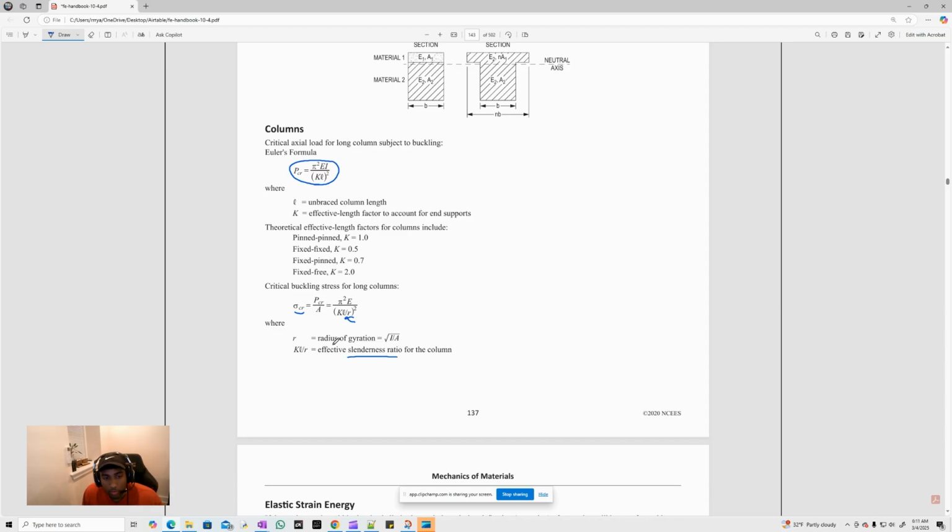You know that a beam will buckle if it's slender. Slender beams have a larger slenderness ratio, which will produce a smaller critical buckling load. So all we really have to do is compare the slenderness ratios about the z-axis and the x-axis to find out which axis it will buckle about. We also see some K values here for the pin-pin and the fixed connection, and note that the radius of gyration is just the square root of I over A.